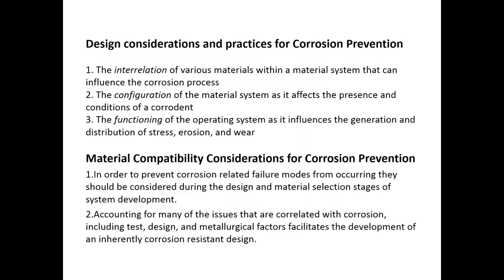Now, corrosion can also be prevented, and this can be done very early on as the structure or the asset is generated. This can be in the form of design consideration, or looking at the material compatibility, that is, preventing anything that can result, let's say, in galvanic corrosion, or using the same material all throughout, or proper design in terms of geometry, flow, and function.